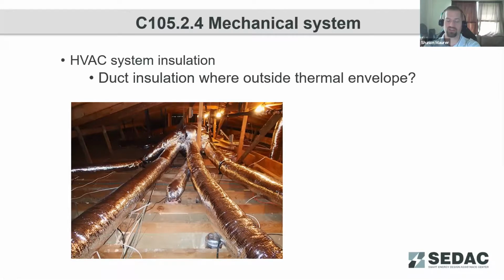Except for high pressure systems where the design pressure in that ductwork is over 3 inches of water, in which case there is a Sheet Metal Manufacturers Association testing standard for that high pressure ductwork. But for most commercial buildings, the duct systems are designed at the 1 to 2 inch range. It's exceedingly rare to see a commercial building with a 3-inch duct pressure design, unless you've got a high velocity system.